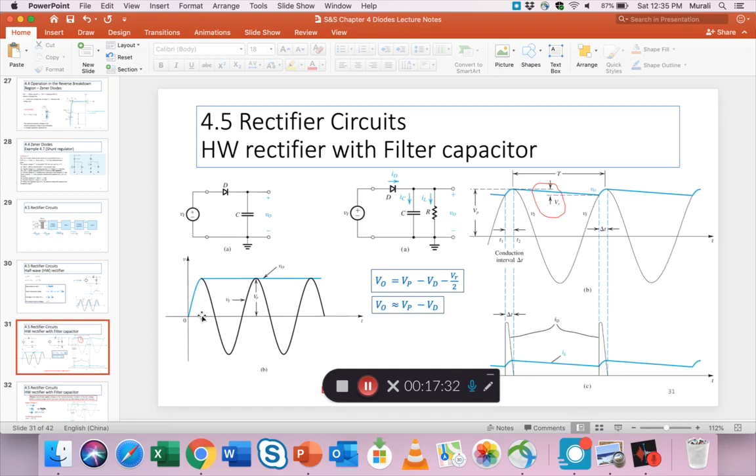Previously it used to be two half waves, half AC sine waves, a positive and then a blocked negative and then a positive. But here with the capacitor, it's almost like a steady output voltage V0 after the capacitor first charges in the first quarter of the first half cycle, and then nothing else at all. It just seems to stay constant. I mean, it's not really constant, it's slightly tapering down, but it's almost constant.